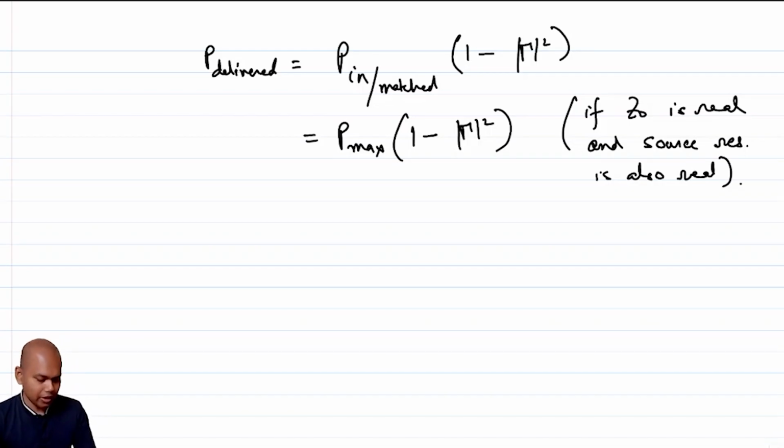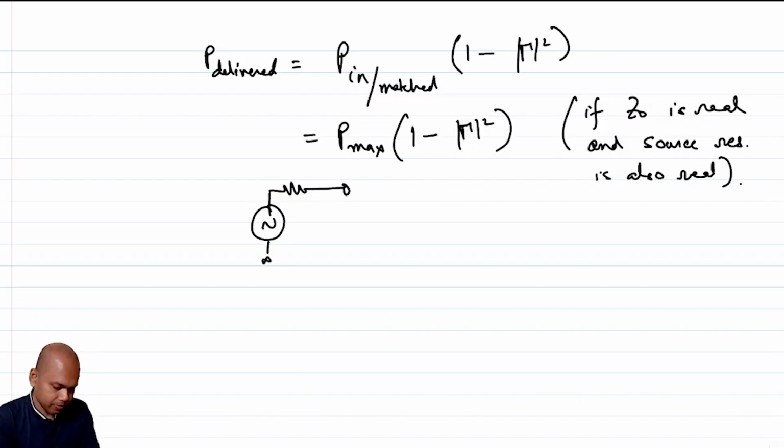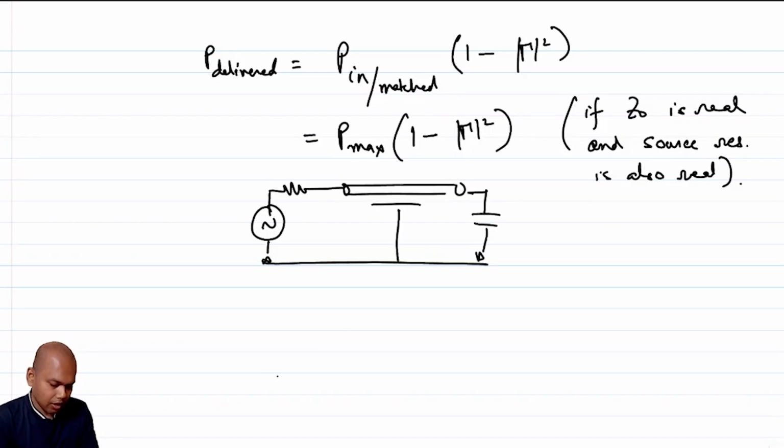Okay. So now this also has some interesting byproducts. I mean this analogy, and the byproduct is as follows. Let's say I have a network and I have a capacitive load here, and I ask you what will be P delivered. We all understand that P delivered should be 0, right? Because the capacitor should not be able to draw any power, and you will see that readily this will come out because of what? Because the reflection coefficient here,